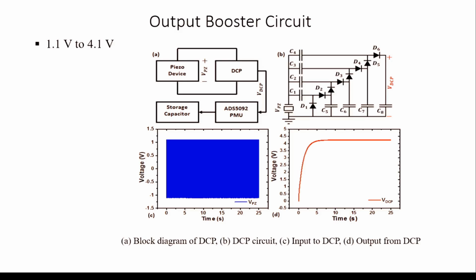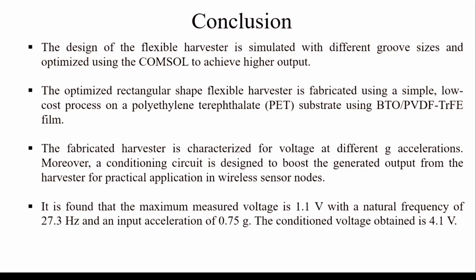With this note, I'll conclude my work. We have designed and simulated different structures with groove design, and used the optimized BTO and PVDF nanocomposite film to fabricate the cantilever energy harvester, and also integrated the conditioning circuit which generates voltage up to 4.1 volt. It has the potential to drive low power sensor devices in future technology. That's all. Thank you.